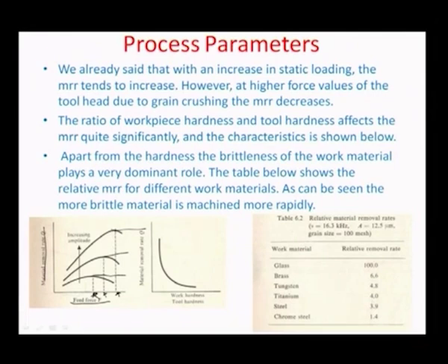It's important to see that if the gap is more, then the critical feed force which would be needed for having this grain crushing effect would actually be higher, because the tool has a higher relaxation time for going from the surface all the way towards this other extremity. The amplitude of motion is more. So if you have more relaxation time, then there is a possibility of crushing to happen at a higher feed force in comparison to if you have less relaxation time in case of a lower amplitude.